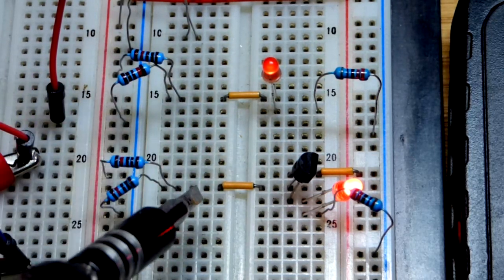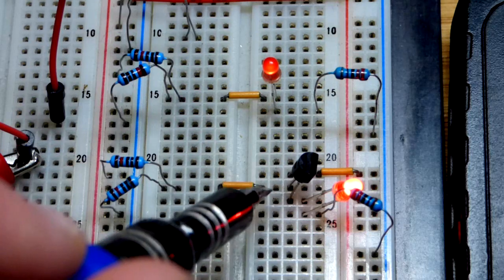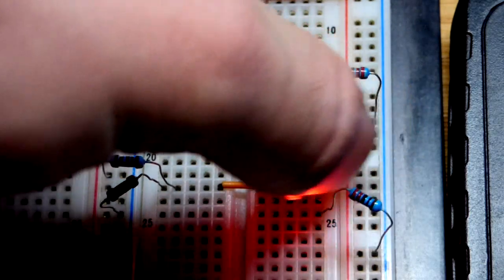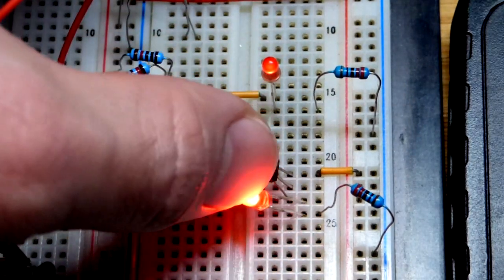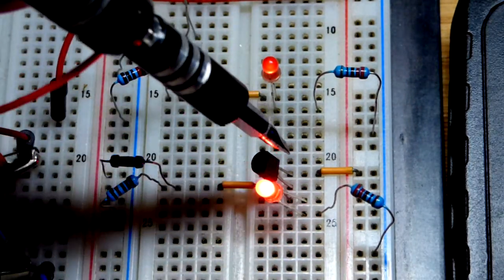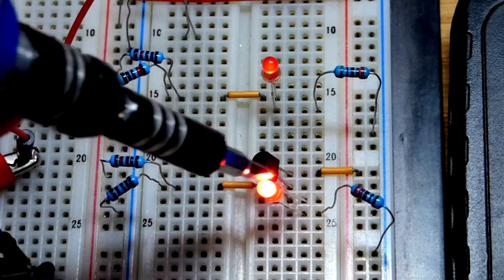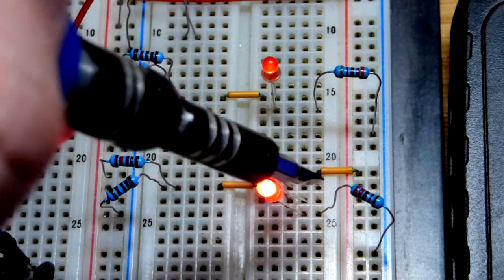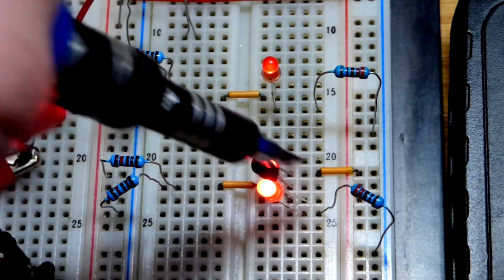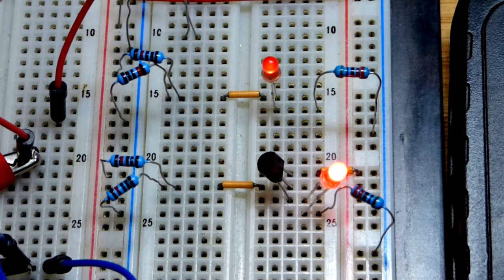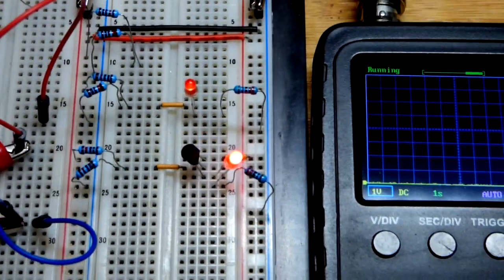Here again, 10 kilo ohm voltage divider to get half the supply voltage to the base, the middle pin of the transistor. And so there you can see we got the flat side there. And so collector on top, or flat side to the right I should say. Collector on top to the positive supply, base, the middle pin to the signal voltage there. And then the bottom pin, the emitter, we got coming to the LED.